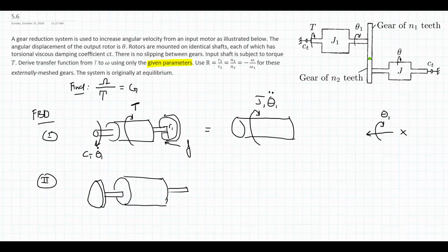Okay, so I need to illustrate on here the moments and the forces that act on the bottom rotor and the bottom shafts. So first, so I don't forget about it, I must have an equal and opposite force. Then this would be the force that the top gear's tooth exerts on the bottom gear's top tooth. So if it's F on the top going backwards, it's going to be F going forwards here. And this force is going to be acting, again, the radius now R2, from the longitudinal axis of the bottom rotor and the bottom shaft. And I'll establish a coordinate system. I will call this the y-axis, even though it is going to be parallel to the x-axis.